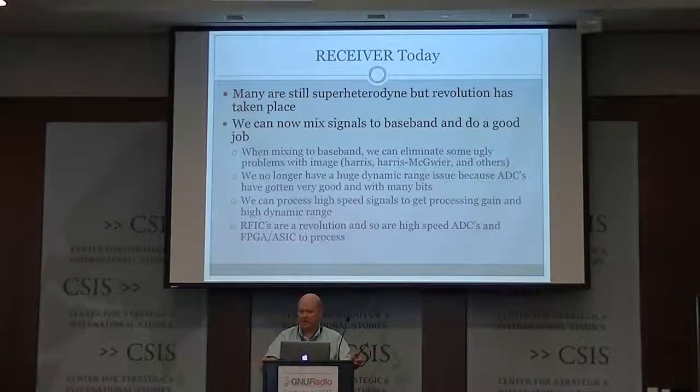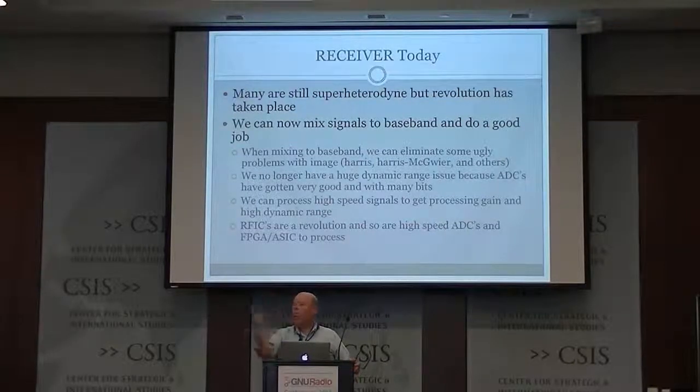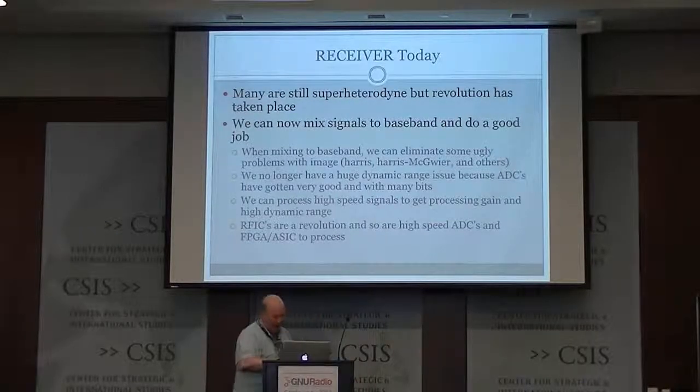The channelization it does is, you have this much signal territory, and you want to only look at a little piece of it. You can focus on what's going on around this little piece, and you get a huge win. By averaging things out, the noise power drops away, you've filtered out noise power, and you increase the dynamic range just by letting your computer look at that piece. So they get very high dynamic range. All of this is very good stuff.